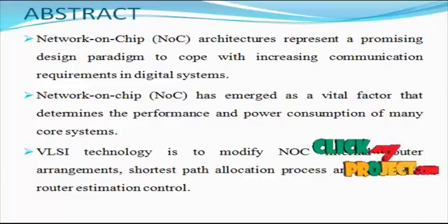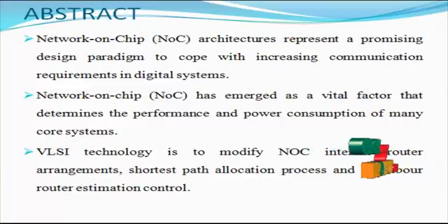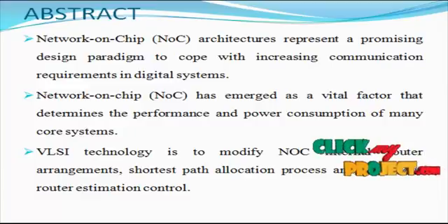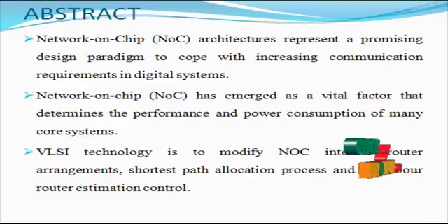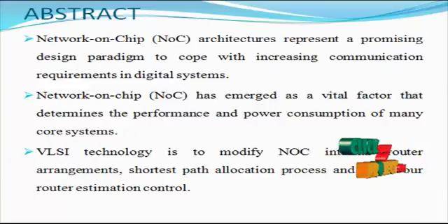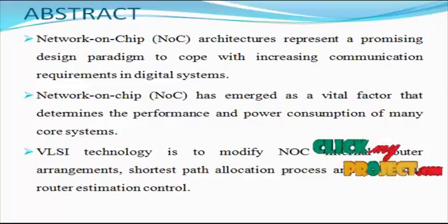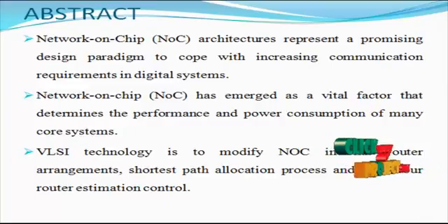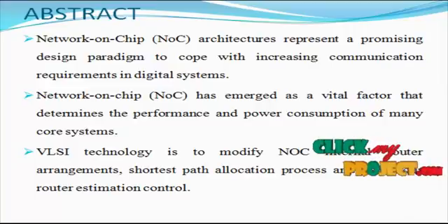Typical examples are the 48-core SCC processor, the 64-core Tile64 microprocessor, and the 80-core Teraflops research chip. All these examples exploit a packet-switched NoC, which brings the advantages of high flexibility and high bandwidth to communications. However, such merit is achieved by exploiting a complex router pipeline.